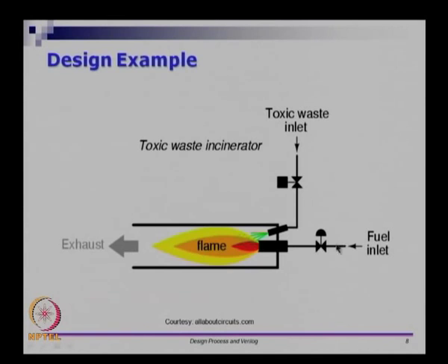So, the issue is we are having a fuel injection. So, there are various things that can happen. So, the fuel itself gets over. If the fuel gets over, you do not want to keep pumping more and more inputs, because the input may go without getting burnt, it may go to the output, you do not want that. So, what we want is, we want to have a mechanism by which we continuously monitor whether there is a flame, and for whatever reason if the flame is not there, we want to immediately shut off this valve so that no more inputs are taken, and we need to go and fix this setup before we can start operating this one.